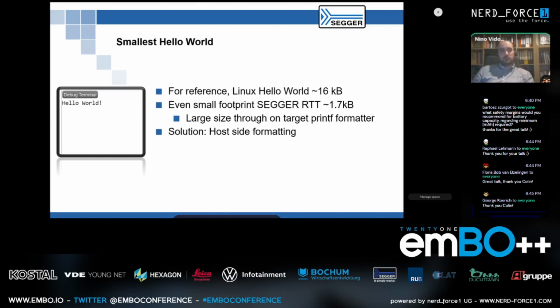So in our case, you can simply switch between different supported I/O channels that are natively supported, which bring different benefits. In this case, it will be code size, because the resulting code for the same hello world that we used initially is suddenly just 281 bytes. If you do some further optimizations in the startup code, etc., it will be even 117 bytes, which I'll talk about on my next slide.